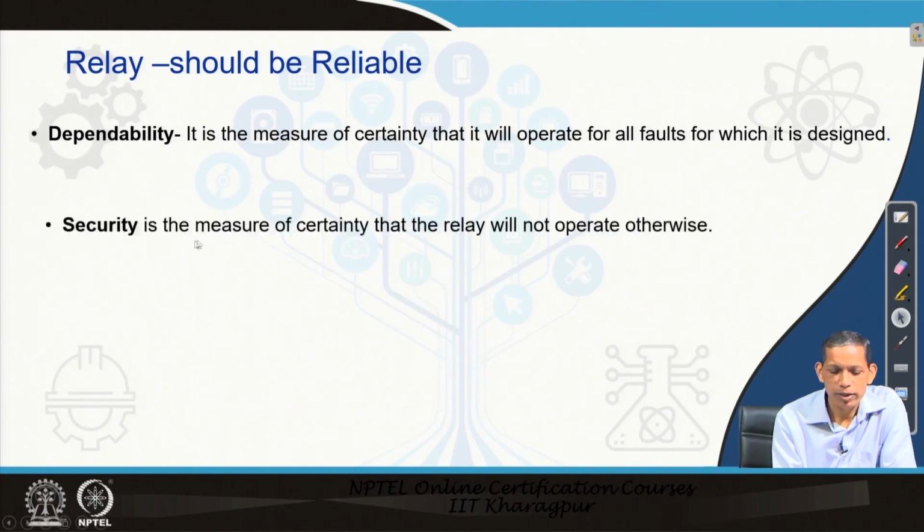The other aspect is security, the measure of certainty that the relay will not operate otherwise. The relay which is protecting a line should not operate during normal loading condition, or if the fault is beyond the line.